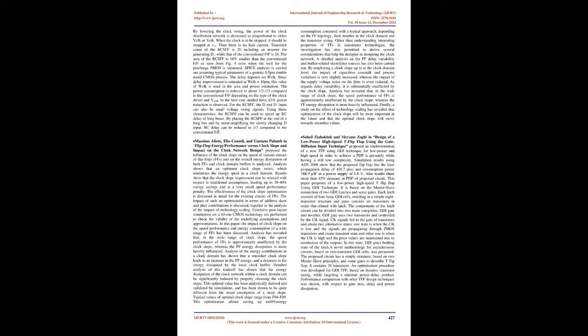188.9 µW in a power supply of 1.8 V. Also, results show more than 45% decrease in PDP of the proposed circuit. This paper proposes a low-power high-speed T flip-flop using the GDI technique.